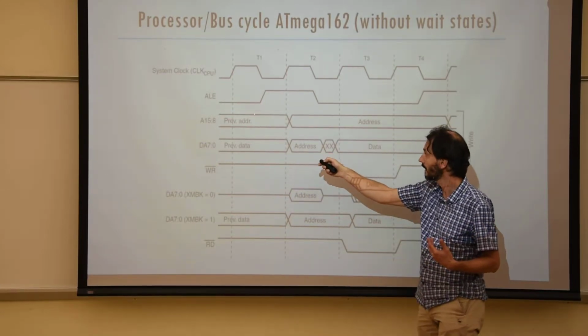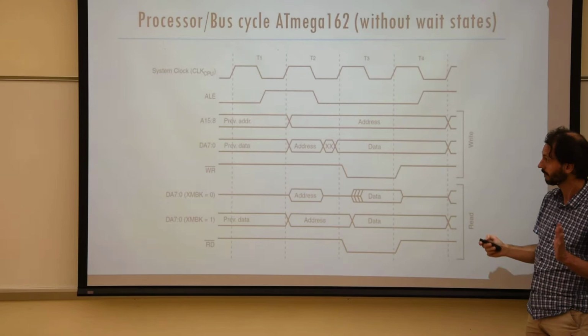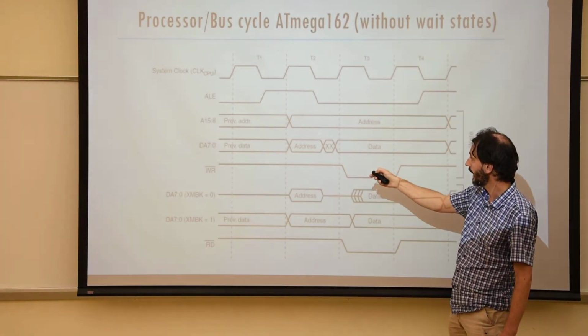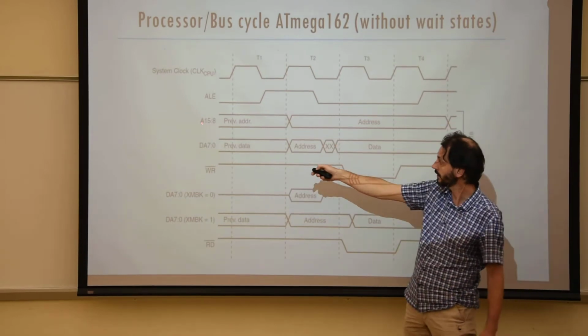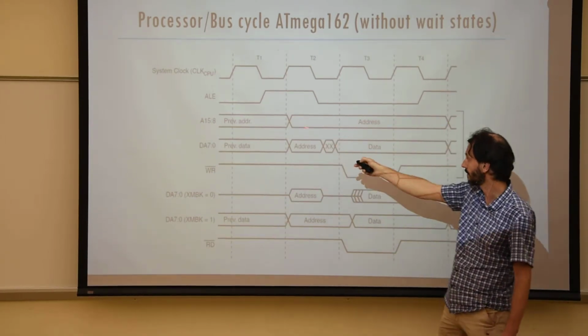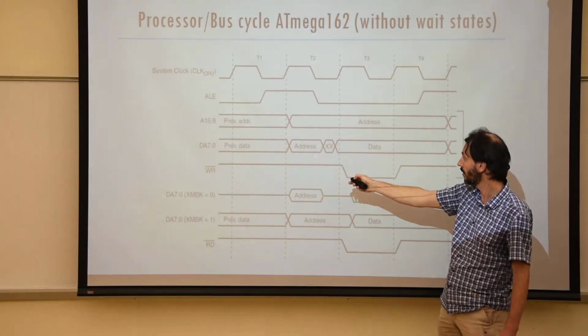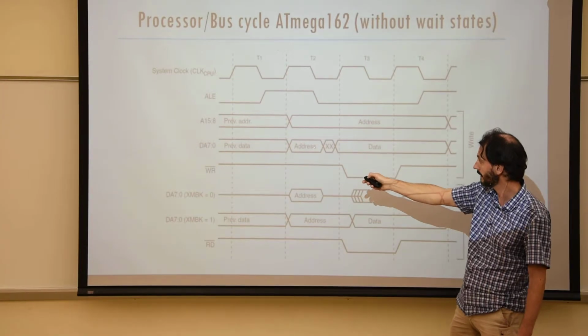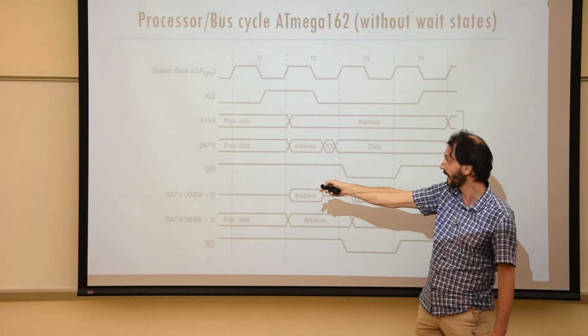Now you're saying, okay, let's start again. Then I put in the address, my current address. Notice it's the 8 most significant bits that I put on here, and I put the 8 least significant bits of the address over the AD lines.